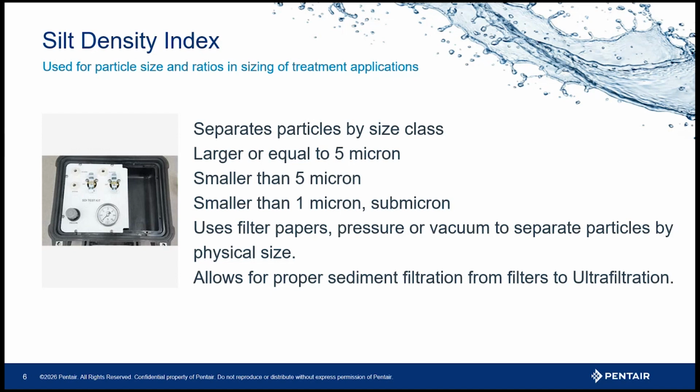Now, quantity and raw water chemistry may require a multi-stage approach. We have run across waters where you need carbon, then anion exchange, to deal with the speciations of the different tannins or different organic acids in the water. I run into that one in Florida quite a bit, where you get multiple organic acids, not just tannins, dissolved in your water. So get a full test done when dealing with dissolved chemicals in the water, not particulate.